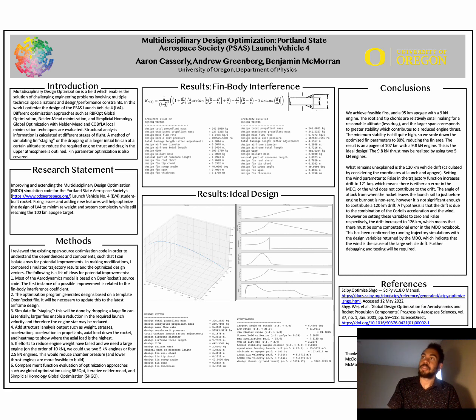And so basically a larger exit pressure was optimal given the more accurate fin body interference, which indicates that what nozzle exit pressure is doing is basically dealing with nozzle overexpansion versus underexpansion.